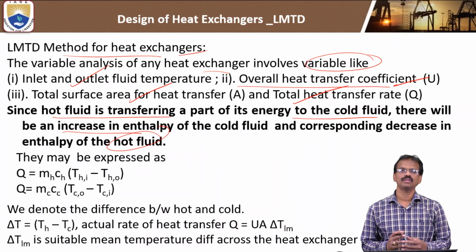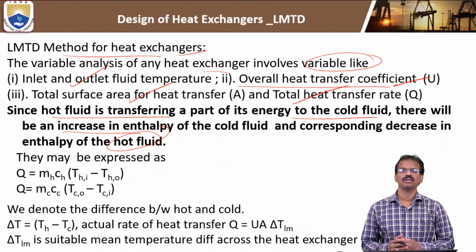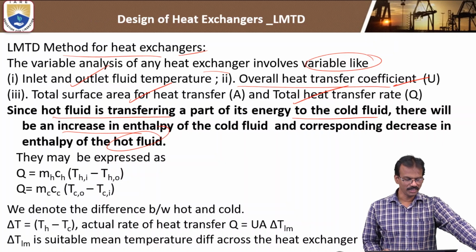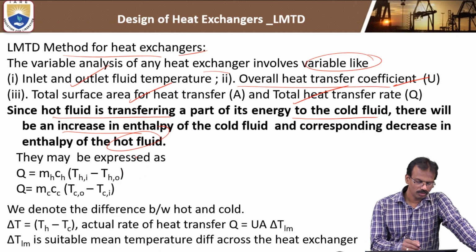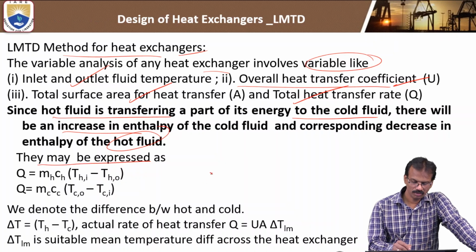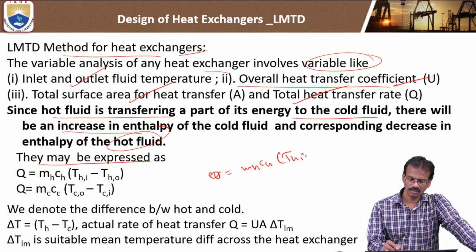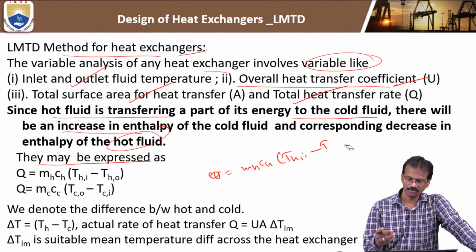So the enthalpy of hot fluid decreases and the enthalpy of cold fluid increases. The formulas, you know this one: Q is equal to, for hot fluid, MH CH into THI minus TH naught. That is the hot fluid temperature difference, hot fluid inlet minus hot fluid outlet.